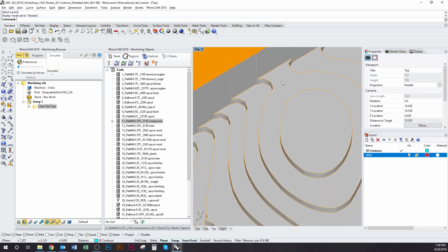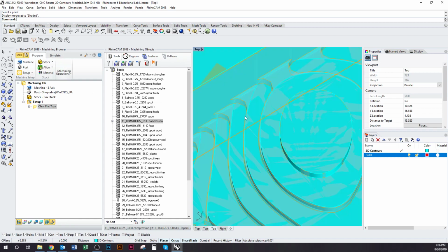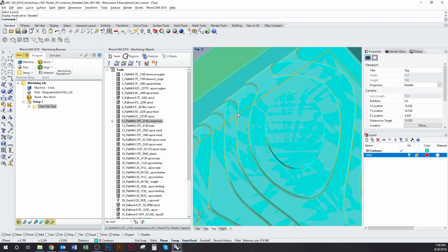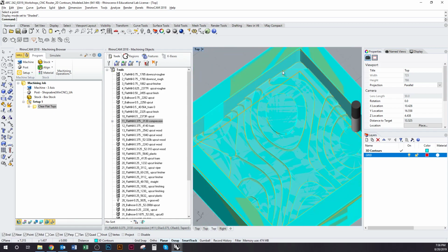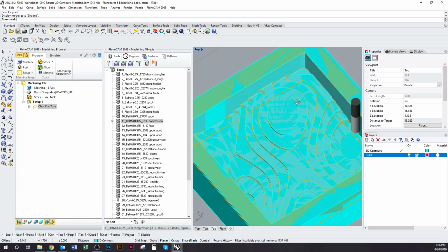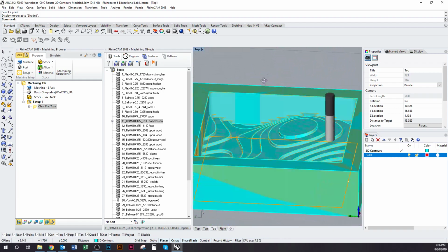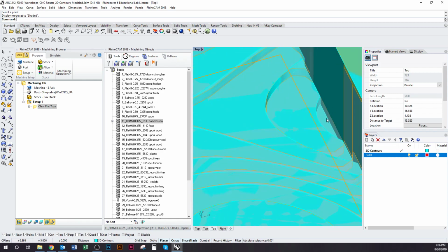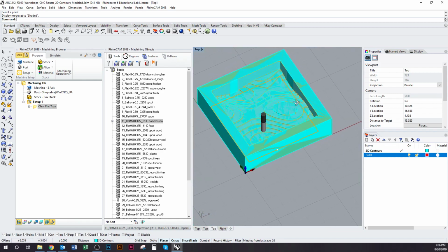So, for example, if we look in some of the corners, because of the diameter of the bit, we're not getting a clean cut between that contour and the outside wall, which is fine. We're just going to have to live with that. So you can see that happens everywhere where we're meeting a certain angle that our bit just can't reach into. And again, this pocket's too small, the router just won't go there.